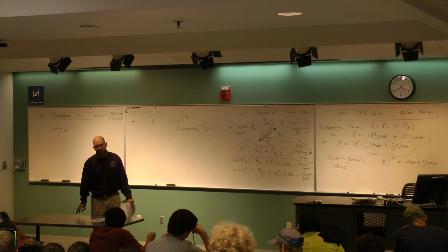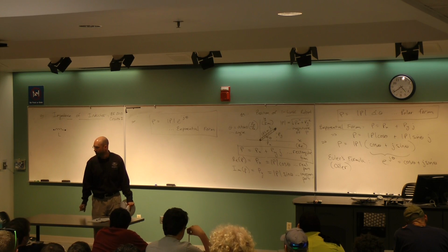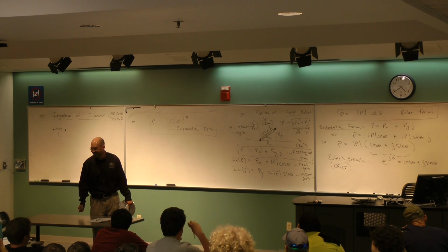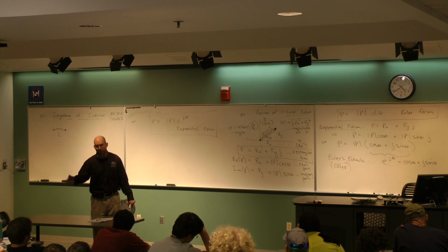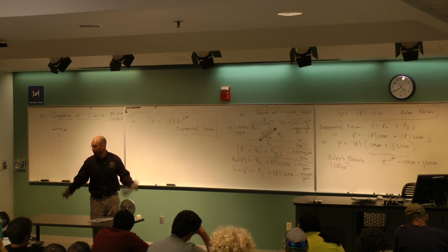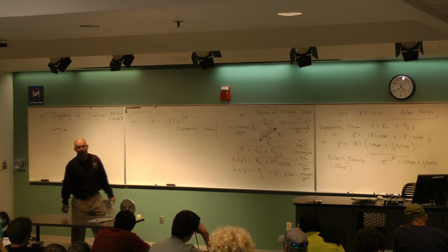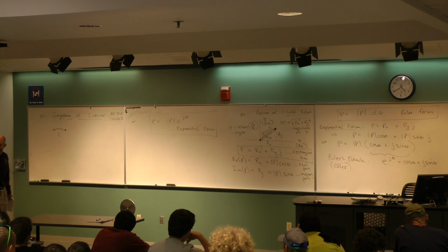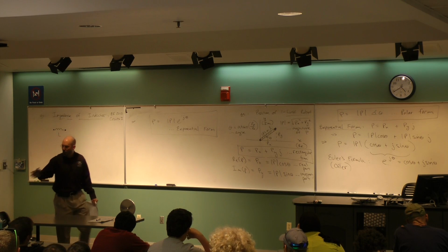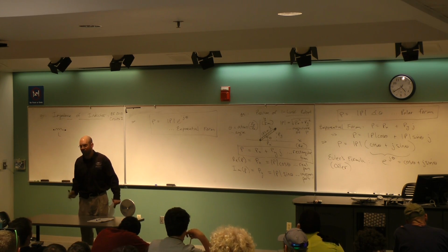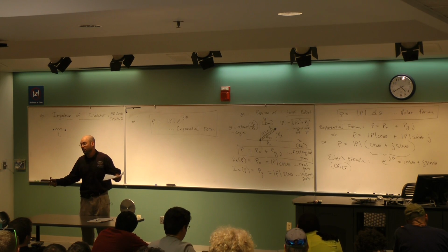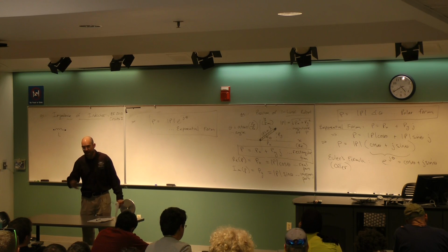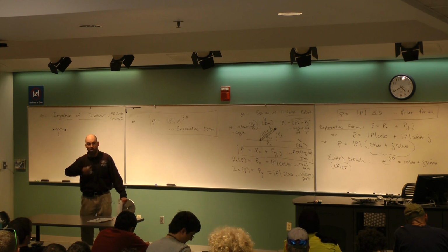Resistance. So here's the thing. What kind of circuit element gives you resistance? A resistor. Turns out all circuit elements have resistive behavior. So I want you to think about impedance as a kind of generalized resistance. And this whole idea of V equals IR, voltage, current, resistance. In general, V equals IZ. Z is my generalized resistance when I have things like inductors, and then we'll talk about capacitors.